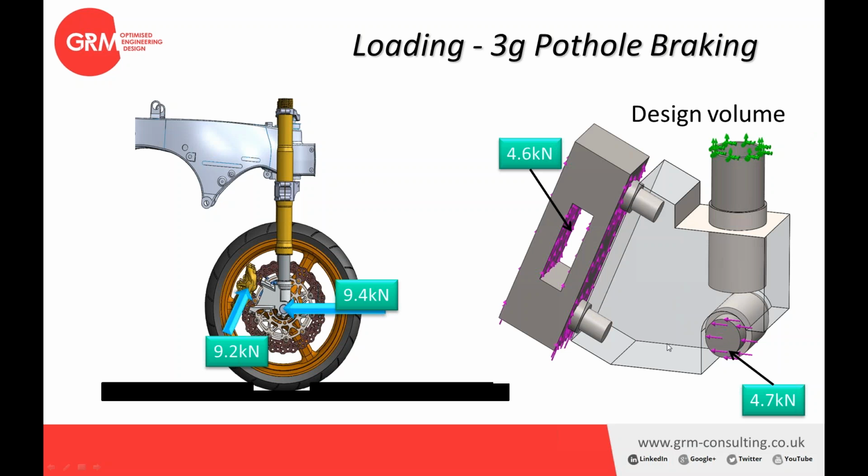So taking a look at how we've considered that in SolidWorks through the simulation module and then preparing it for TruForm, we've designed here, as you can see, a fairly blocky design space for the brake caliper component, and we've put non-designable regions, so separate bodies in our solid part, for where the axle fixes, the threaded insert for the bike fork, and then the caliper mounts themselves. And we've applied the load of the brake calipers via this generic representation just to put the force into the fixings. We've fixed the bike fork end and applied also the axle load to the bike axle.